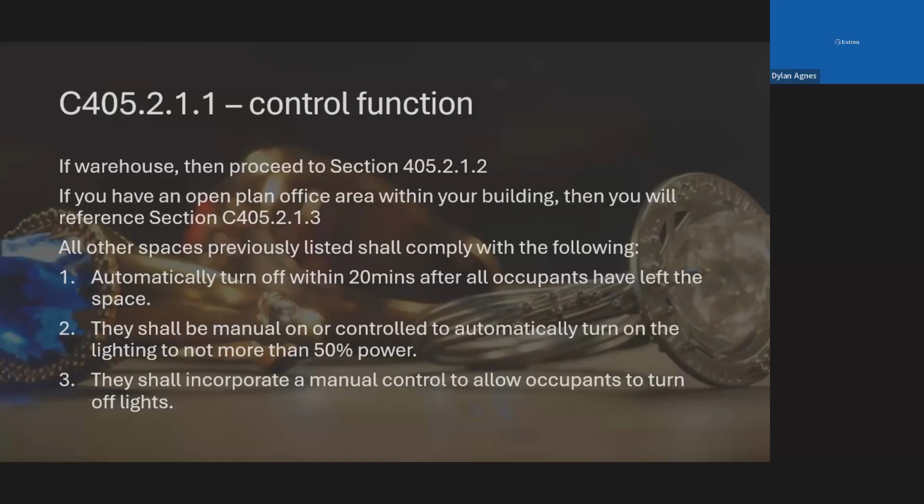You decide that, hey, I'm actually going to stay in this space. I want more. Because the point of the occupancy sensor is to reduce energy, right? But where I have typically seen it used in the industry and application is for occupant comfort, where it's like, yes, turn it off when I leave the space, but when I come back to the space, turn it back on to the way I had it in the last set point that I used. That's what ours does. So that's typically what I see, but again, that's not what it's supposed to be.